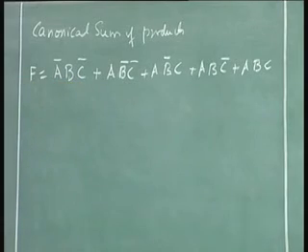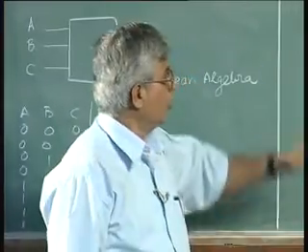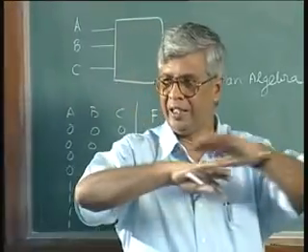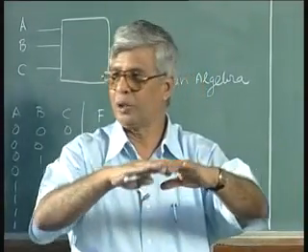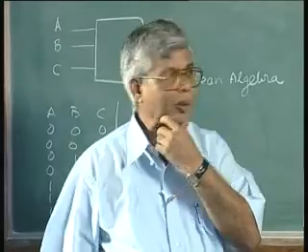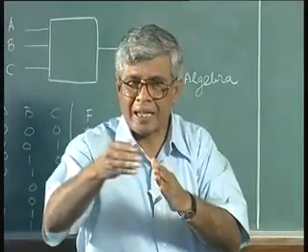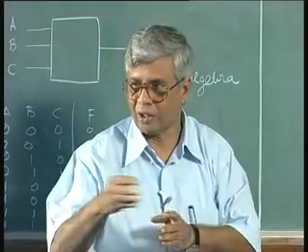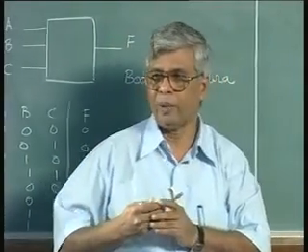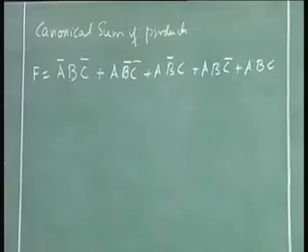The other combinations are the combinations for which the output is false. If you write it in this form, this is a canonical sum of products because all the input combinations for which the output is true are expressed in this form. It is called a sum of products because it looks like product terms combined by a sum series. Even though we are referring to AND and OR operations, AND is loosely referred to as a product operation and OR is loosely referred to as a sum operation.